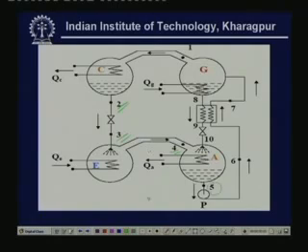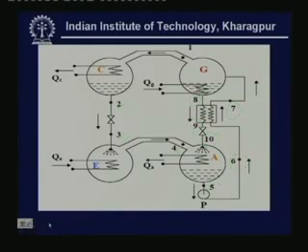Point 5 is weak solution at evaporator pressure. Point 6 weak solution at generator pressure. Point 7 preheated weak solution at generator pressure. Point 8 strong solution at generator pressure and generator temperature. Point 9 is strong solution, so now cooled strong solution still at high pressure. Point 10 is the strong solution at evaporator pressure. So, now we will find out the properties of all these points, because if you want to find out the performance we need to know the properties.